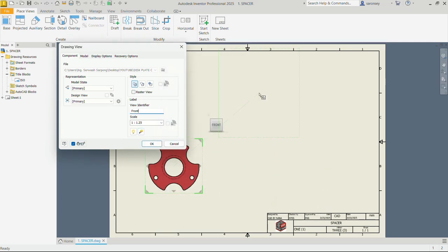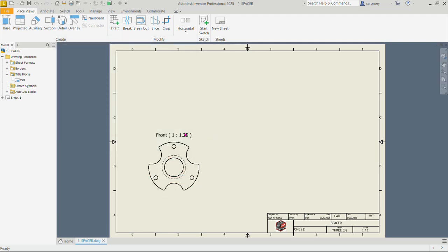And OK. Let's also take notice of the view cube here. You can use the arrows next to it to orient the base view as best as you deem fit for your detailed drawing. You can even get the isometric view with the home button here. But I'll keep these details and OK for now. If you want to replace this text here, you can just click once it turns red and drag it down.